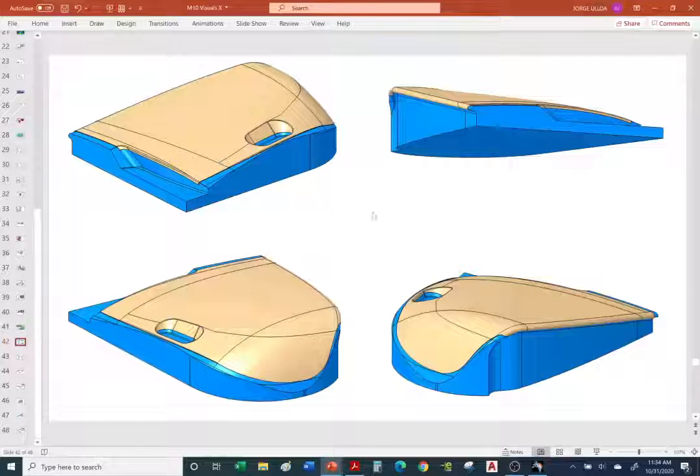Also with sheet metal, sometimes when you have to form a flange, like this flange here, there's this thing called spring back when you try and form a piece of sheet metal. So it gets this angle here. Sometimes it springs back. So sometimes you have to change the size of this wall, or scale it so it'll overshoot, and then when it springs back, it'll actually spring to the position you want it to. Okay, so that's scaling.